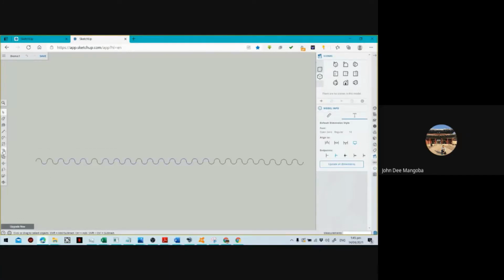We only need the parts. So there, it removed me now. Click on one of the edges and then just drag it a little. Then on your keyboard or your number pad, just press 0.05 inches or 0.05 double apostrophe and then press enter. So now there's an offset. It has made a copy.